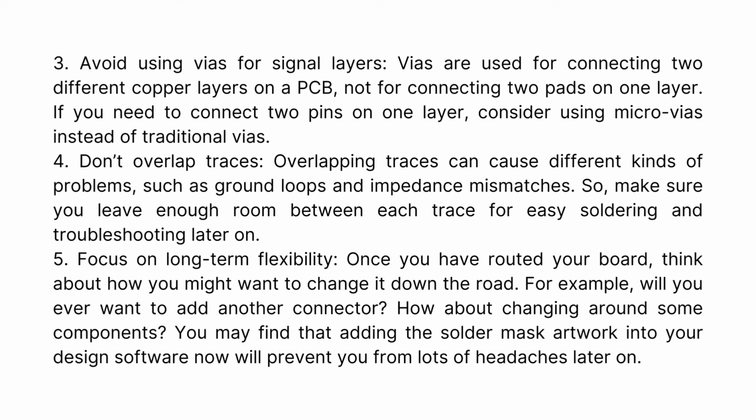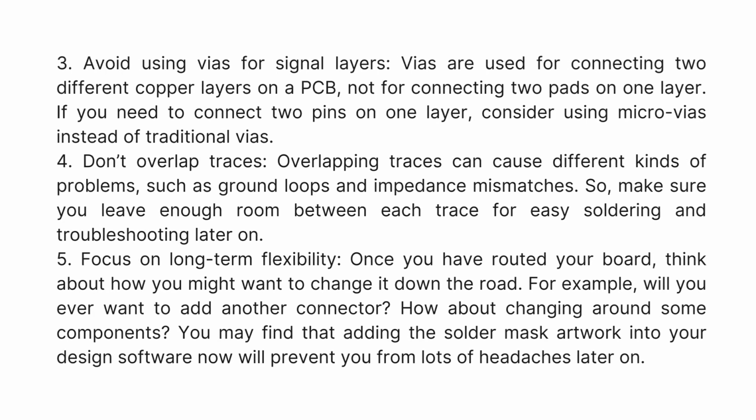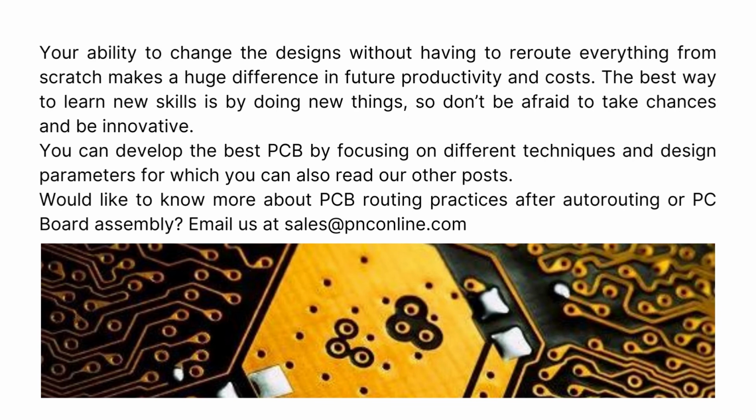5. Focus on long-term flexibility. Once you have routed your board, think about how you might want to change it down the road. For example, will you ever want to add another connector? How about changing around some components? You may find that adding the solder mask artwork into your design software now will prevent you from lots of headaches later on. Your ability to change the designs without having to reroute everything from scratch makes a huge difference in future productivity and costs.